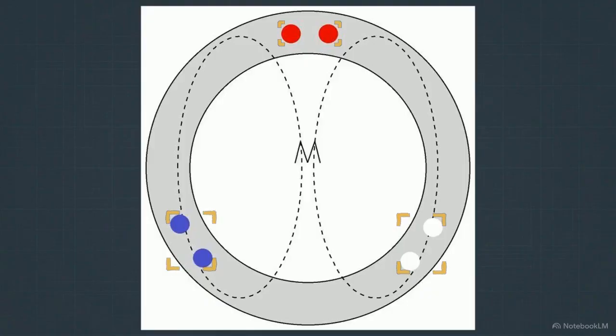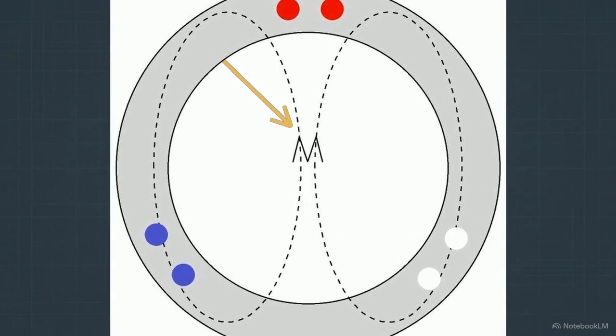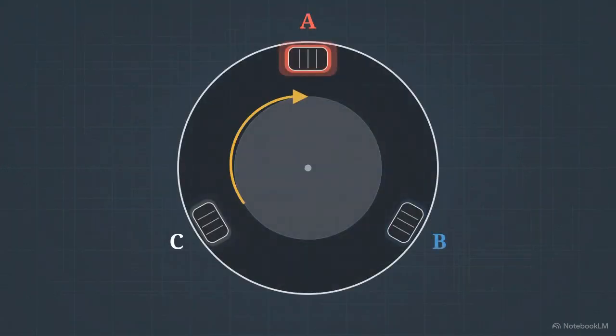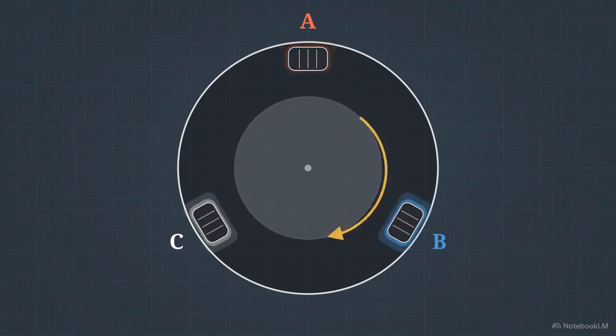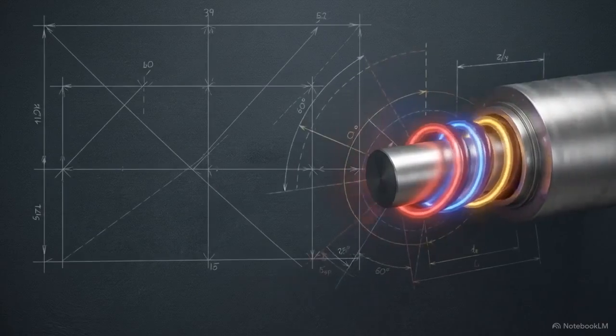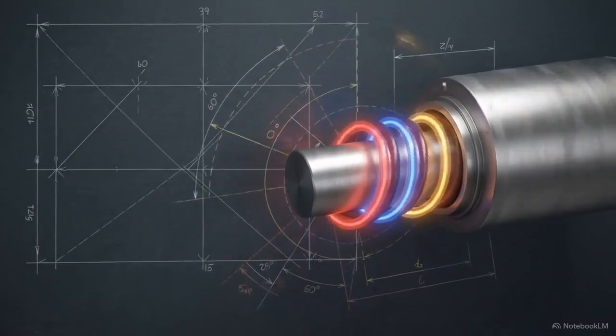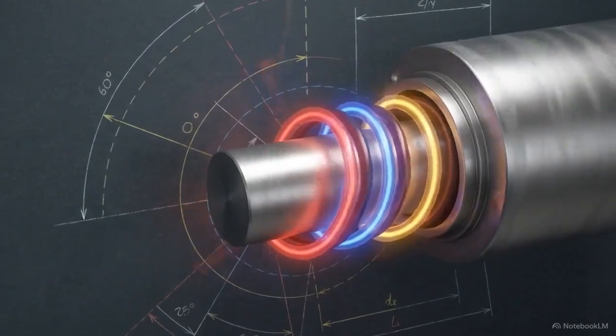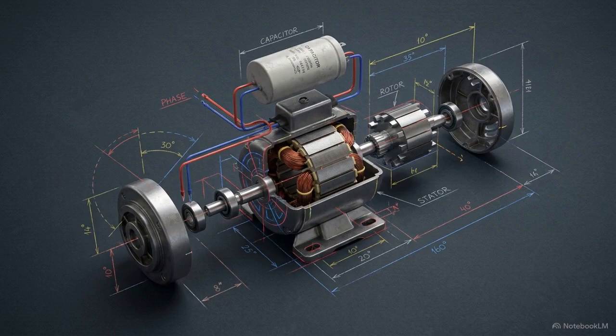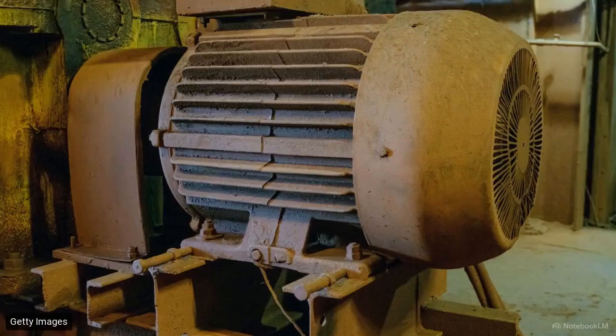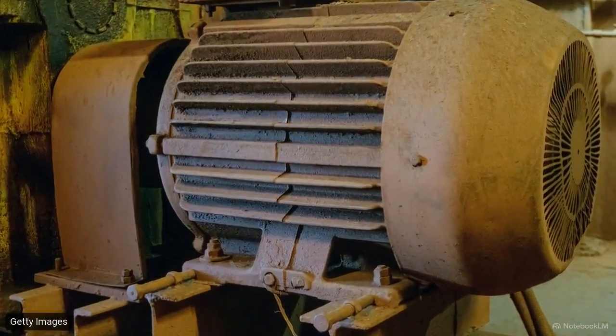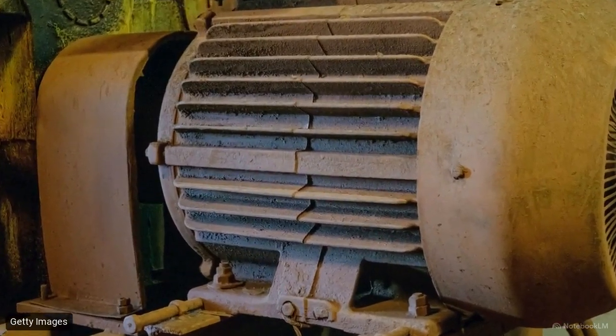When you connect a motor to a three-phase supply, those electrically staggered currents automatically translate into sequentially staggered magnetic forces inside the motor housing. Because the coils are spaced around the housing, that 120-degree electrical delay naturally generates a magnetic field that physically rotates in a circle. This continuously rotating magnetic field reaches in and drags the central metallic rotor along with it, creating instant motion. Single-phase motors struggle to start spinning on their own, often requiring extra starting capacitors. Industrial three-phase motors, by contrast, are inherently balanced, self-starting, and mechanically superior.